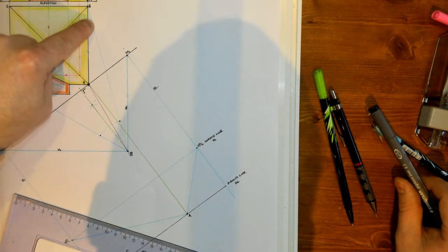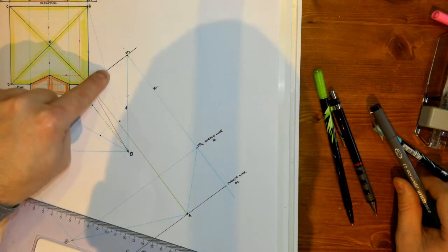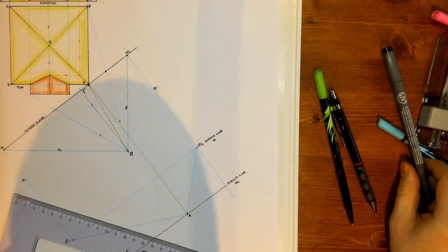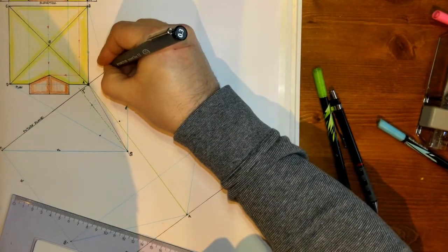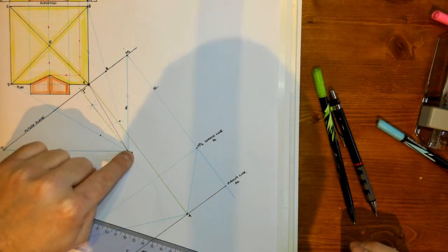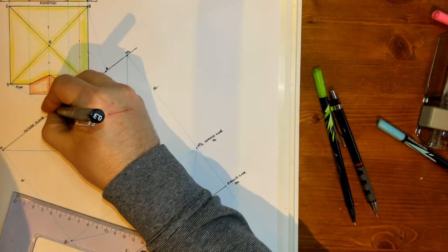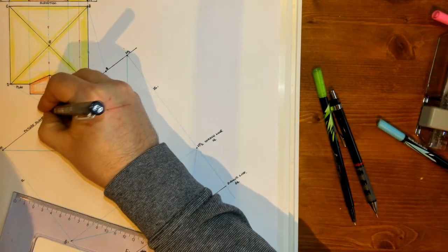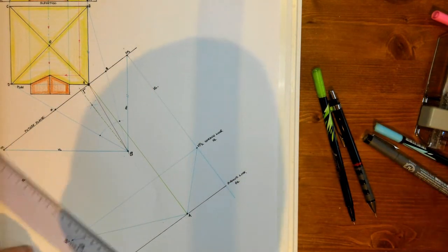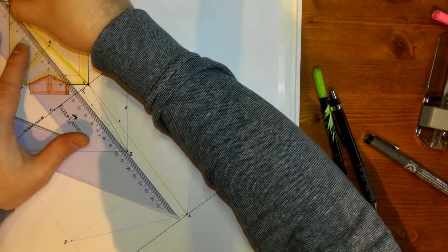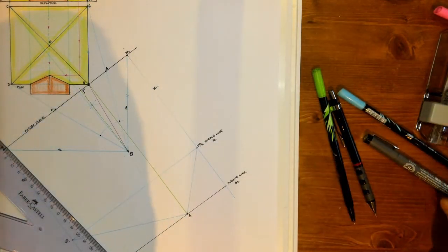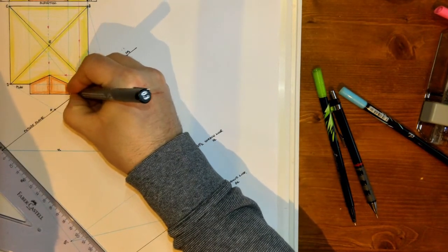So, point B, we already have a line coming back to point S. Where it crosses the picture plane, that's the point we're interested in bringing down. Okay? So I'm going to write that now as point B there. Point D is brought back to S, okay, as we originally did. Where that point crosses the picture plane, that's point D. Okay? And then we have point C, which I need to bring back. So I'll take point C, I'll bring it back to point S like so. And where point C crosses the picture plane, well, that's point C.